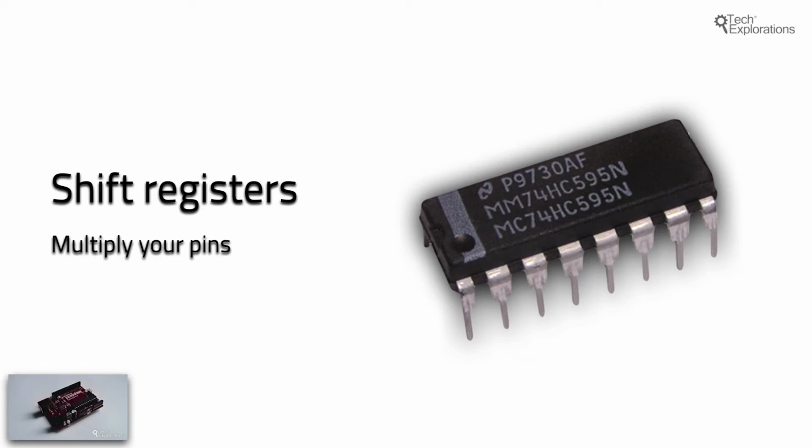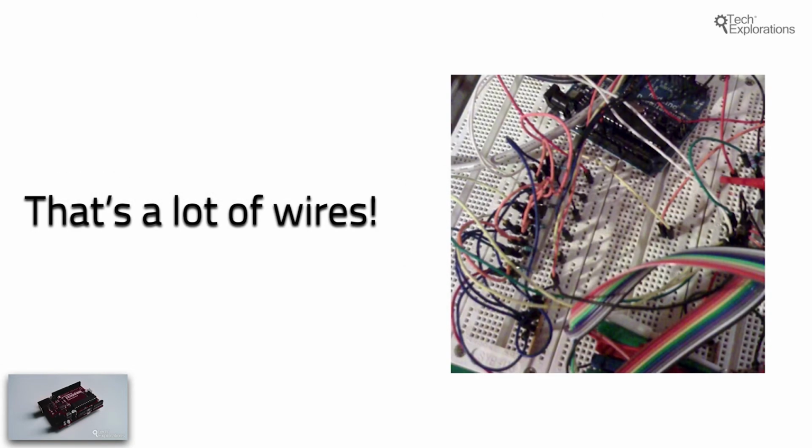Take for example the case of a gadget that contains a character LCD screen, a couple of status LEDs, a couple of buttons, a couple of sensors and a Wi-Fi breakout. You'll need 2 pins for the screen using the serial to parallel adapter, 2 for the LEDs, 2 for the buttons, at least 2 for the sensors and 6 for the Wi-Fi breakout. That more or less exhausts the available ports. Sooner or later, you need a way to multiply the available inputs and outputs so that you can connect a larger variety of peripherals.